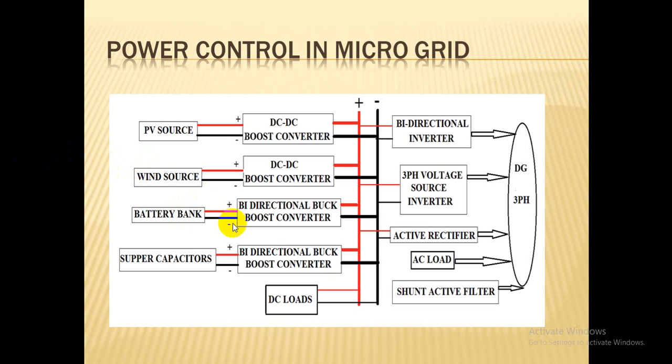So see the source side itself, all the power modules like the boost converter and then the bidirectional buck boost converter can be controlled in a single FPGA, but there is no effect or interruption of these pulses to those pulses. So why? Because it's parallel execution in nature, and also the FPGA has more IO lines, so without any problem we can interface all the power modules. You can generate more than hundreds of PWMs, more than 200 PWMs.